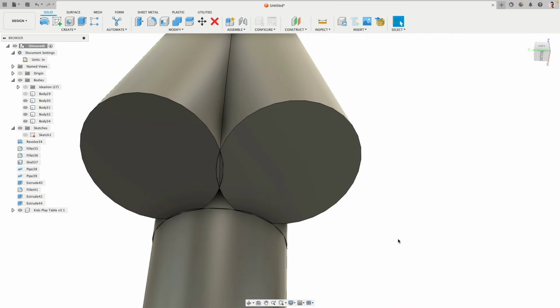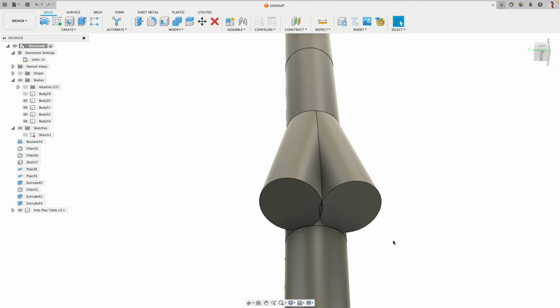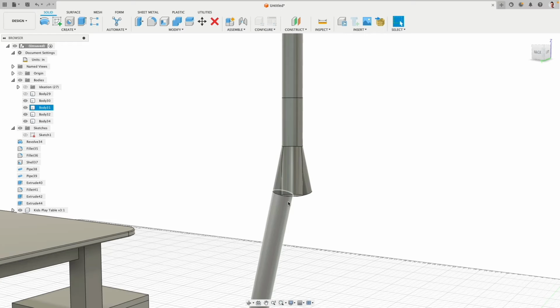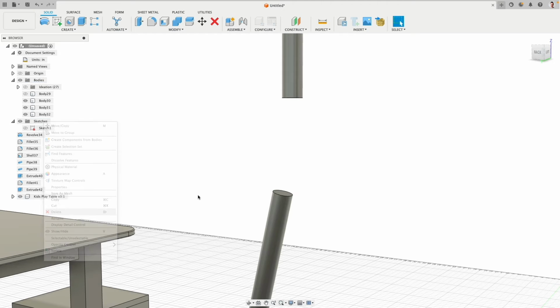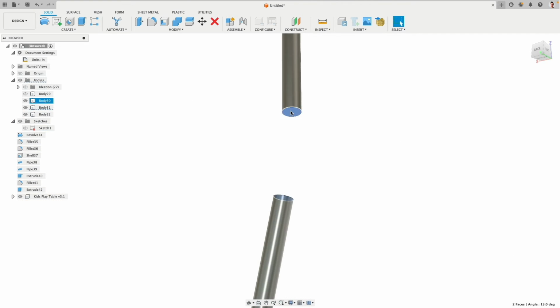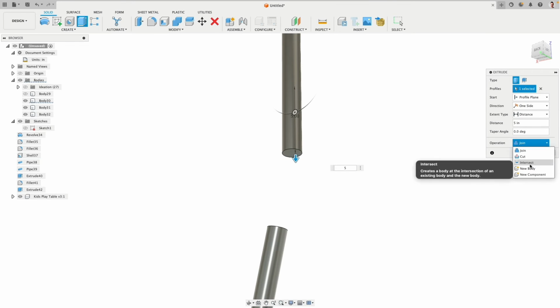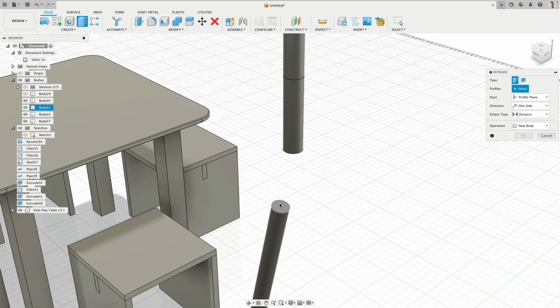And there we actually can see, oh, nah, that doesn't work. These pieces are intersecting. So that means everything needs to be further away. So let's add 2 more inches. So this is kind of like a good example of prototyping, where you have an idea and then you start modeling, and then, well, you notice, doesn't work as much yet. So we set here -2. Very good. Now, keep in mind, this goes down 5 inches. And the same here.